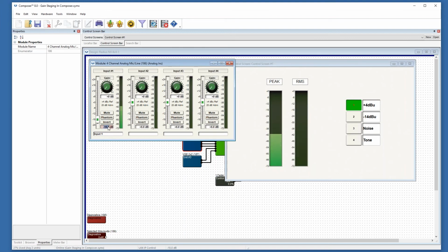Let's go negative 20, actually, because I already have it set for 0 dBFS. So now we're at negative 20, so it's at the typical level you would want to see normally on a meter. But you'll notice, because it's peak, it gives us the level that we're used to seeing, hitting roughly right around negative 20 dBFS.